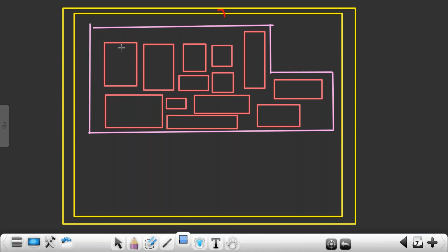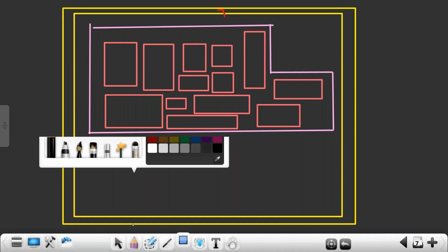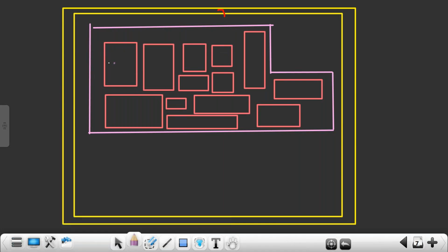Here each block is called a block. Each block has a cell count, and each block level engineer will get a separate netlist. He will get his netlist, and you should do the physical design of your block. A subsystem lead will take all the physical design blocks, integrate them, and form a subsystem. And the full chip level designer will integrate the subsystems and send the GDS to the foundry. So this is how the partitioning happens.